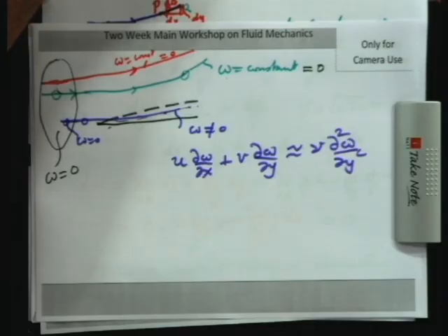In the previous interval we had shown that in the outer region of the flow the vorticity value is a constant along a streamline, and since the upstream is a uniform flow with a 0 vorticity, the value of this constant is 0. So, for any streamline in the outer region which is starting from the upstream region here, omega is 0. Now, we will give a physical interpretation to that.